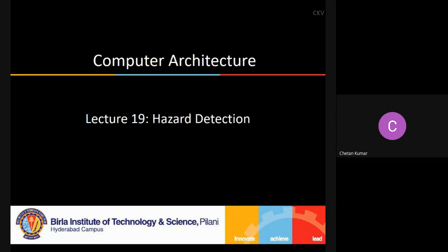So it's basically about the write register value. The write register number is supposed to be supplied by the instruction which is there in the write back stage. So you have to make sure that the write register number moves along with the instruction. Then you route the write register number through the pipeline registers, and connect it to the write register port of your register file. So that was one modification.